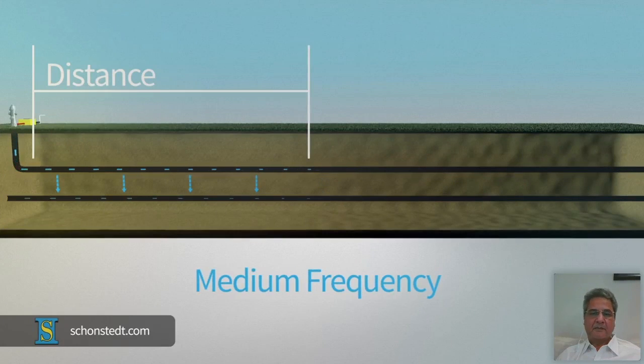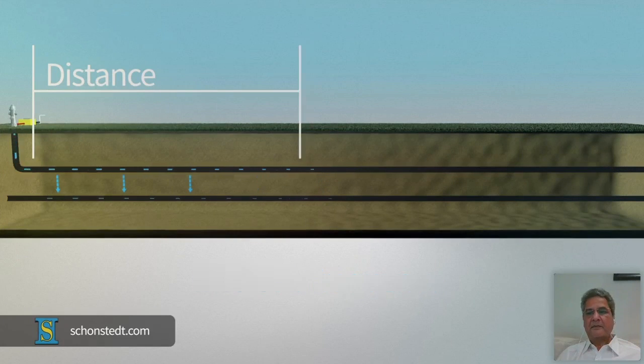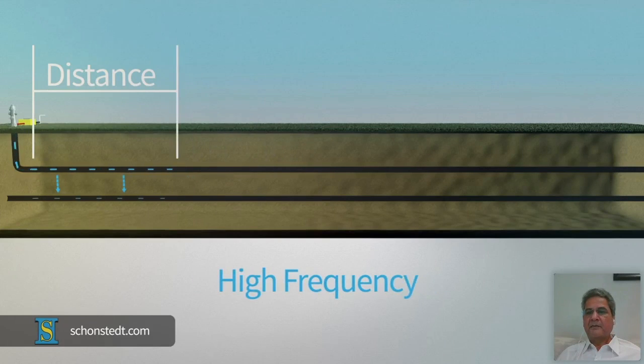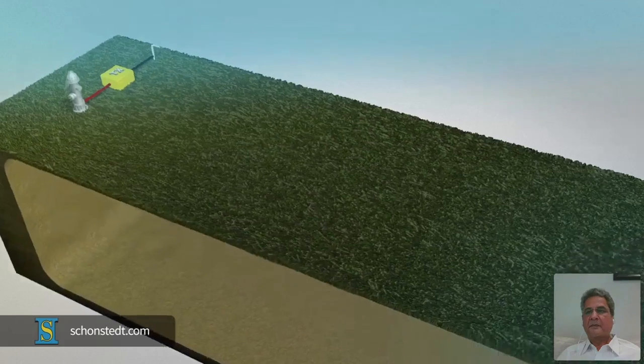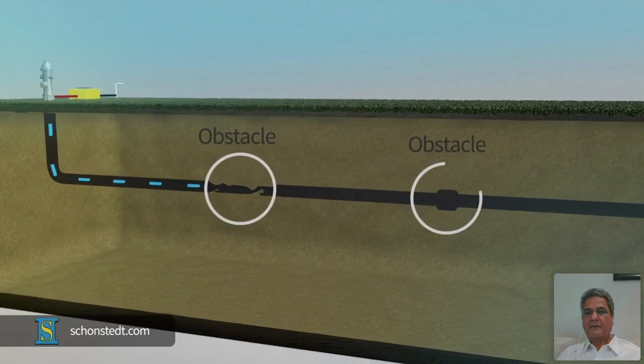And remember, at higher frequencies, the current will leak to the ground quicker, which may impact your ability to accurately locate. By contrast, poor conditions, poor conductor, corrosion, non-conductive joints, etc., necessitate the use of higher frequencies to overcome potential obstacles.